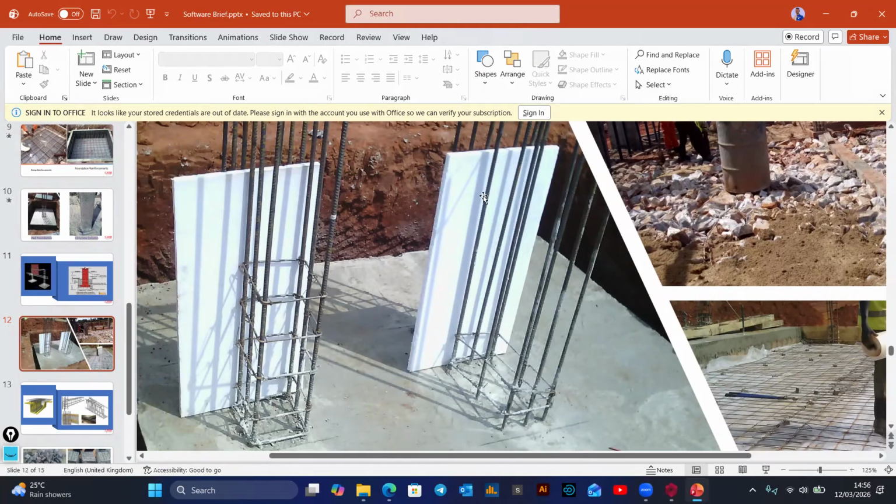But then the white membranes you are seeing there, those are expansion membranes. Usually when we are designing a building which is too long, there's need to provide expansion joints, such that in the event of maybe any lateral loading, or maybe the building has developed cracks, those cracks are not transferred to the rest of the structure.